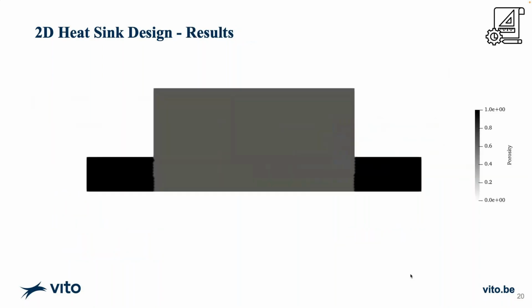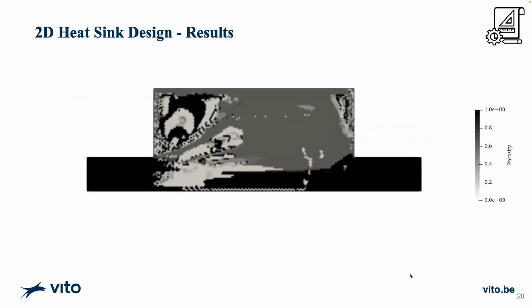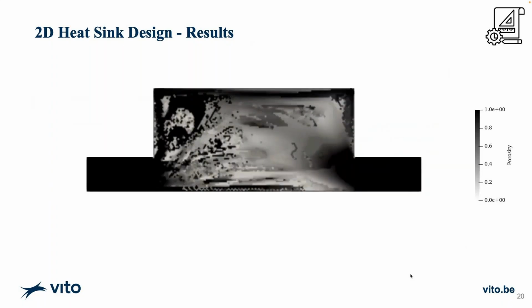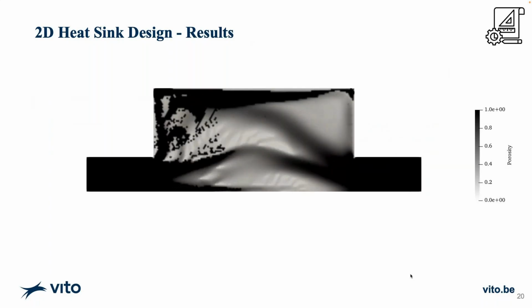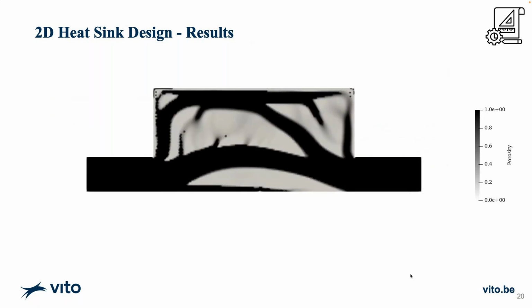But nevertheless, if you look at the designs, again, similar thing to follow in the case. The dark regions represent where the fluid can flow, and the light regions is where is the solid. So we can see it starts with a very interesting approach. Maybe the graphics are not very clear. So it tries to create these branching structures that you can see in the tree, but it doesn't have the capability to convert them. And as you start tuning your Q more and more strict, it quickly converges to a local optimum. And towards an optima, which is